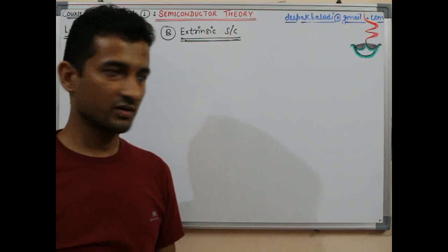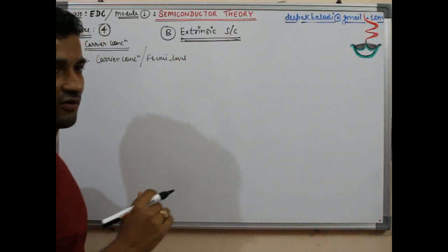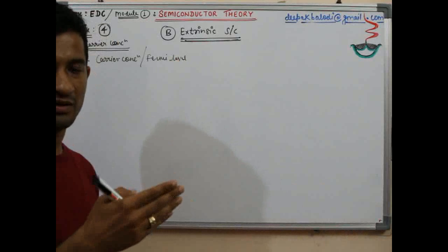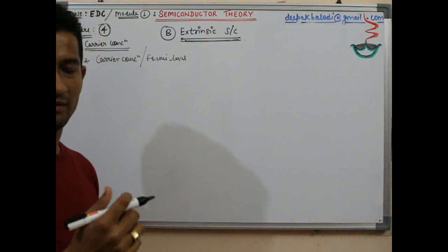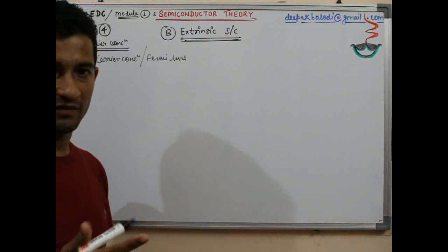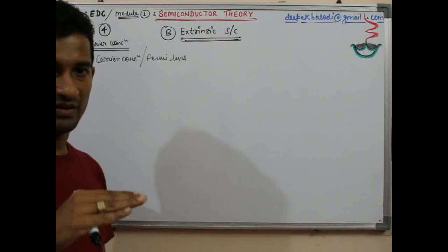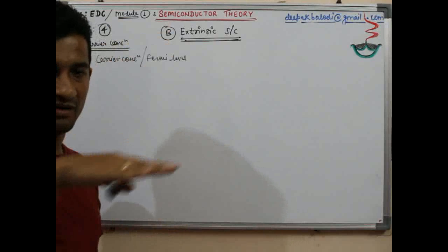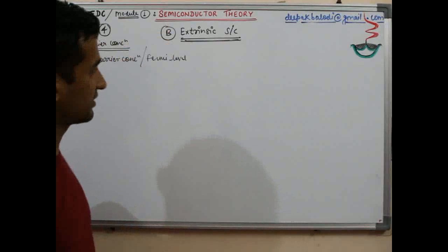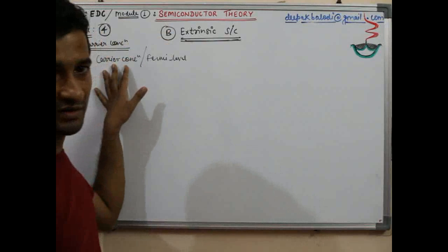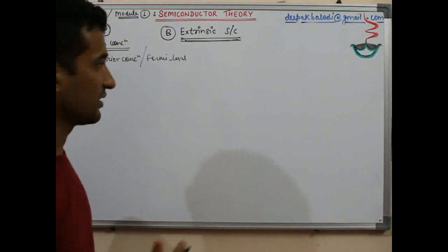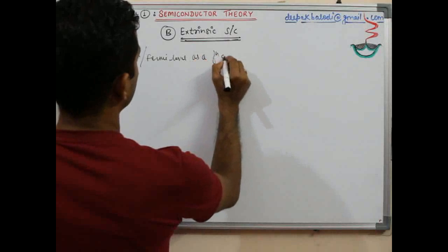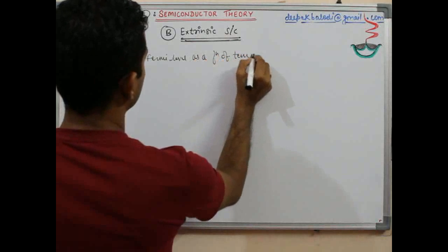Now a small comment on the carrier concentration and nature of extrinsic semiconductor as a function of temperature. The final Fermi level of an extrinsic semiconductor is the indication of final carrier concentration, because with that only we can identify how much impurity doping we have done. If the Fermi level shifts much higher than EFI, the center value, then we can expect that the final carrier concentration of the majority carrier is much higher. So let us see this as a function of temperature.